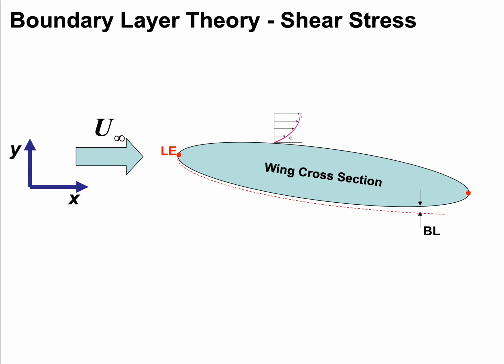So we have a boundary layer, and once we start talking about the no-slip condition and the velocity differential between the surface of the wing and the free stream, then we need to talk about the shear stress, because the shear stress comes from the straining of the fluid, so the strain rate of the fluid. You see the fluid is moving in this picture at different velocities at different locations, and that relative motion creates a transfer of force due to viscosity, which we call shear stress.